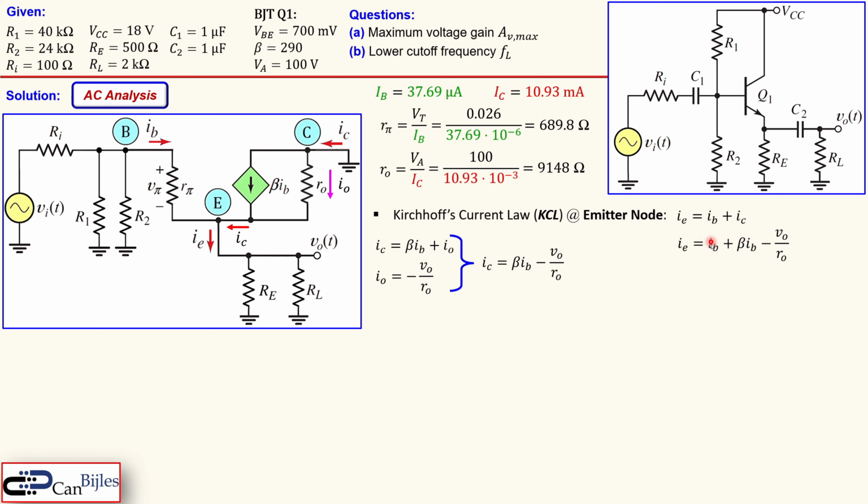So that is actually the expression where you normally see, but now we have the additional part because of this early voltage. So we have now this, and also additionally this part. Now we can continue looking at the voltage at the output, which is VO. Well, the output voltage is the emitter current times the parallel combination of these two resistors, RE and RL. So this current will flow through this effective resistance here.